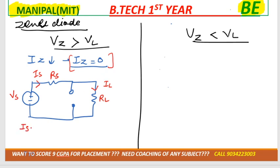So what can we write down? Is is equal to IL, right? Or according to Ohm's law, Is is equal to V by R. V is what over here? V is Vs divided by Rs plus RL, because now Rs and RL are connected in series. Correct? So we can use this formula, and in this case VL is not equal to Vz. Okay, because the Zener is open circuit, so its voltage and the load voltage will be different.